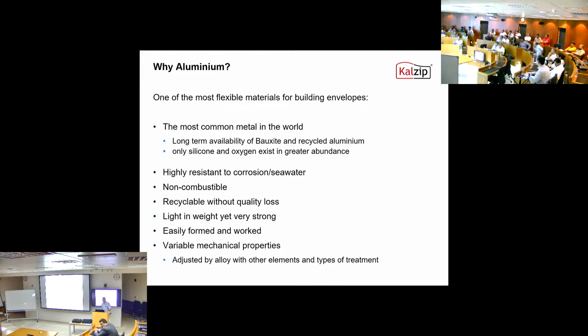If it's an ACM panel, the ACM filler will burn, but the aluminium won't burn, if that's what you mean. But our 3000 series, per IPC, aluminium and wood are classified as limited combustible, unless you treat them specially to upgrade them to non-combustible.